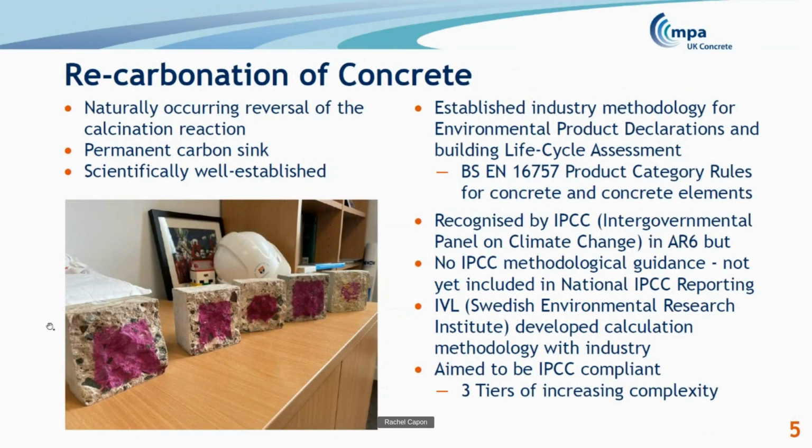Okay, so recarbonation or carbonation of concrete. Obviously the chemistry is a lot more complicated than the simplification that I presented, but we can conceptually understand it as the naturally occurring reversal of the calcination reaction. So once the cement is incorporated into a concrete or another product such as mortar, it starts to reabsorb the carbon dioxide, and it's a permanent carbon sink.